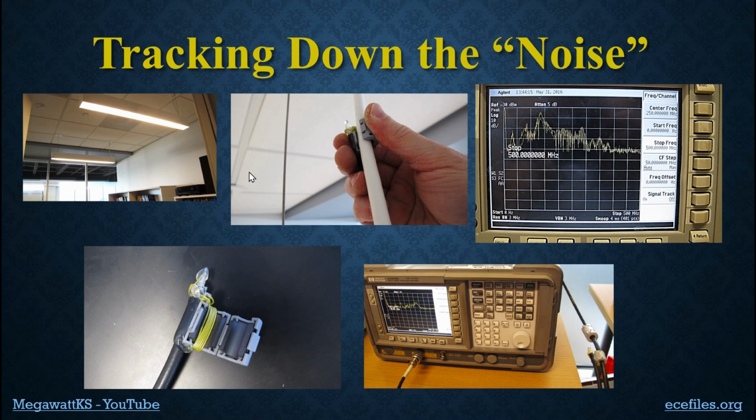So here I was looking at how much is the conducted emissions from these lights. I wasn't worried about radiated emissions because theoretically they've passed some controls there. But I'm worried about conducted emissions because they probably didn't have the same wiring that we have, and I wanted to measure it. So I came up with this little probe.